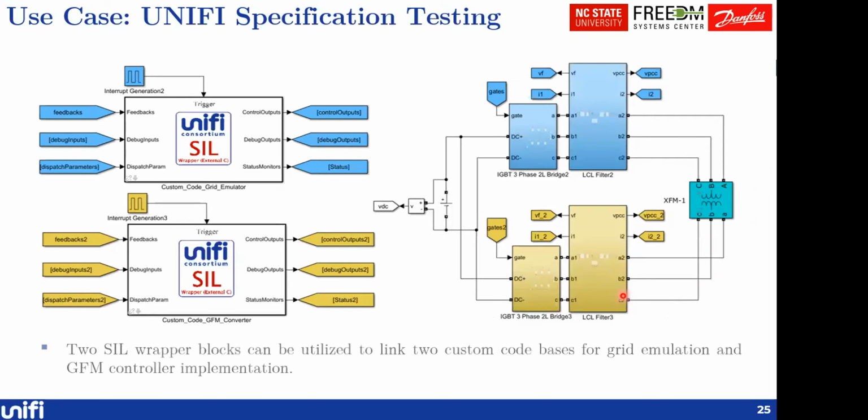And again, this SIL simulation tool will actually help to build this model first, and then test it out in the simulation and look at the interaction first before implementing it in the hardware test platform. So these are a couple of the use cases and the simulation demo models that we are working on, and we hope to use these wrapper blocks for validating different control architectures, as well as evaluate a wide range of inverter operation scenarios before transferring them over to the hardware test platform for further validation.